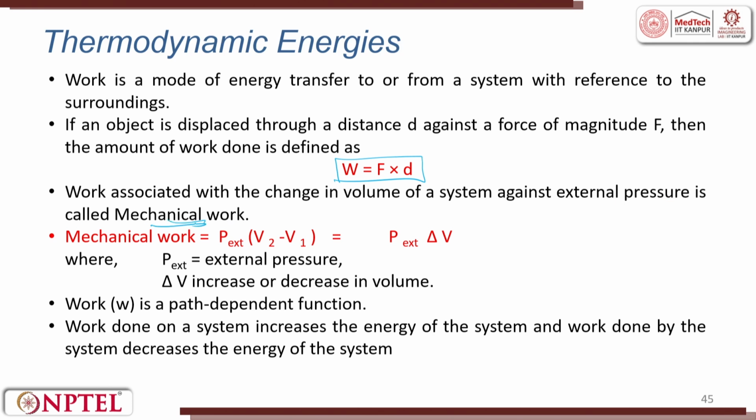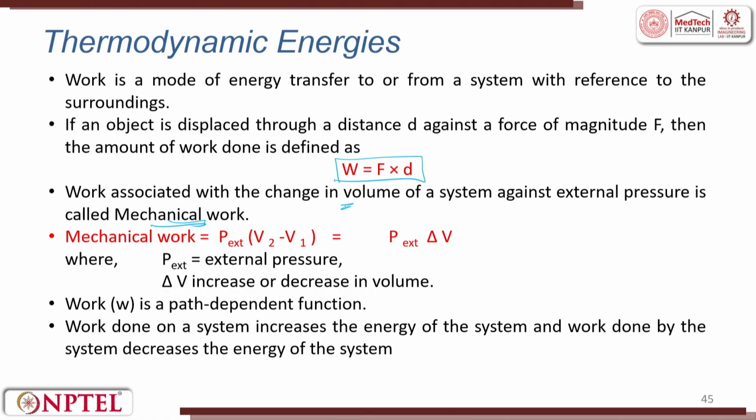Suppose there is a piston, there is a dead weight of the piston. Now you heat it, the volume expands. So now delta V is the change in the volume of the system against the external pressure. What is the pressure here? Here it is nothing but the load, right, the piston load. So that is mechanical work.